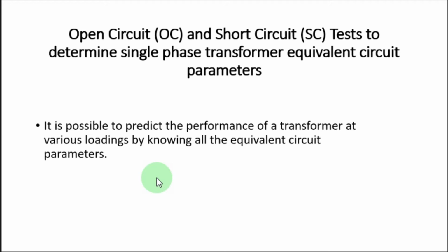And this flux is again linking to the primary side, and it has some impact on the primary side as well, right? Therefore it will reduce the magnetic flux on the primary side, and then the back EMF will be reduced, and due to that more current will flow into the primary coil.